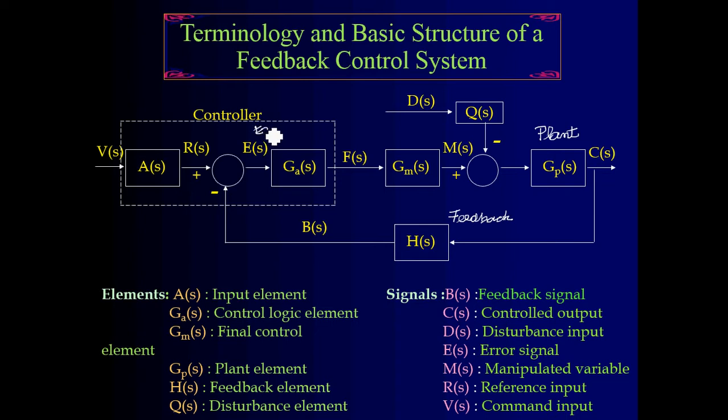Let's write it down. The error there. Depending on what the error is, you need to do the correction. This could be the dial on the thermostat, if it is a thermostat, or some number that you set to measure what you want. This transforms it into a voltage. So these two voltages get compared, and the difference is called the error.